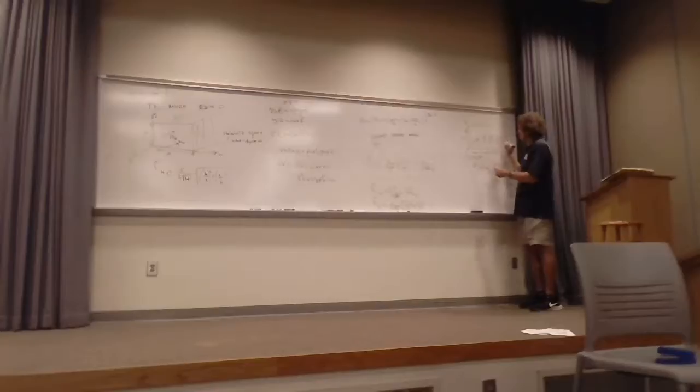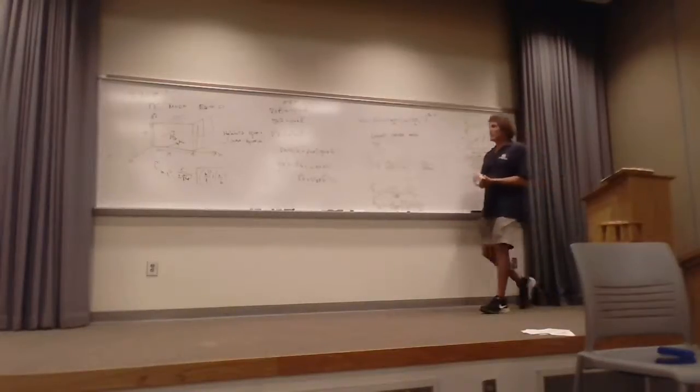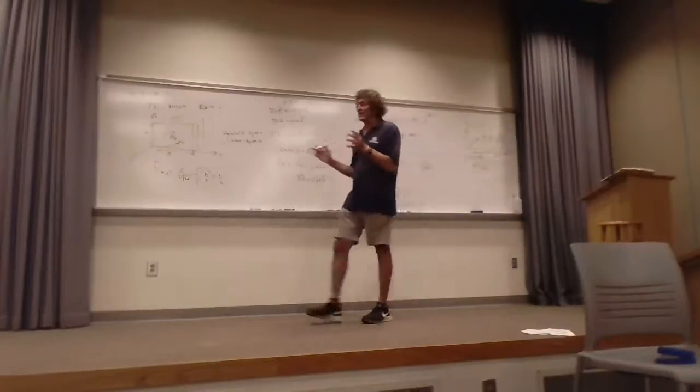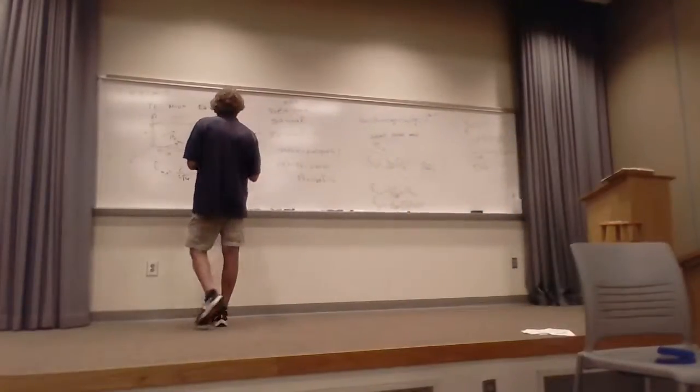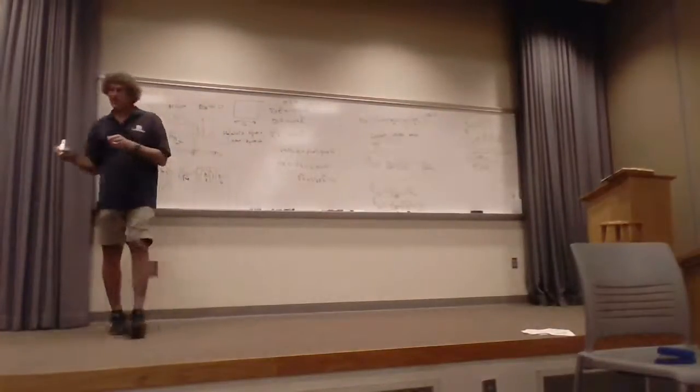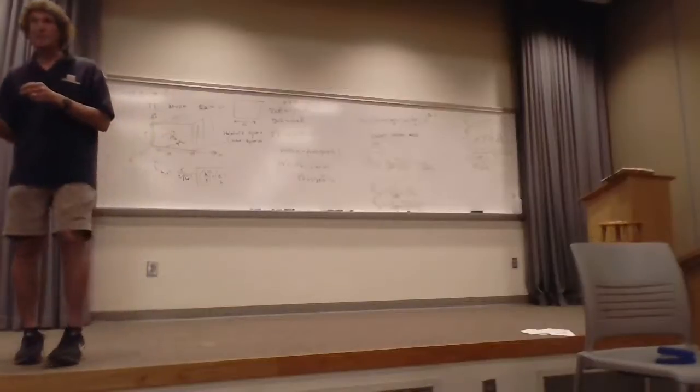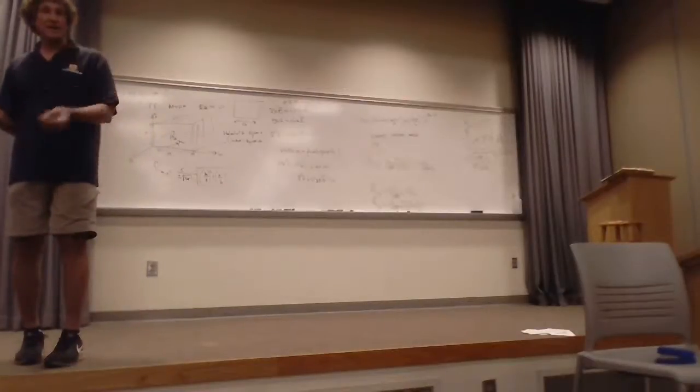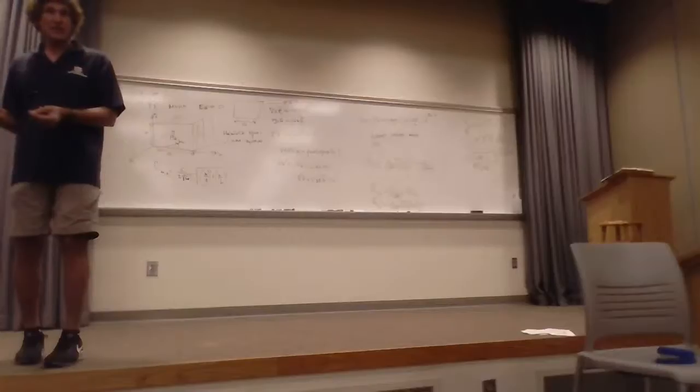And it looks like this, and this will be the actual cutoff frequency. The lowest order mode will be the cutoff wavelength by 2. So it's exactly a half wavelength long. So if I want to know what the cutoff frequency of a rectangular guide is for the 1-0 mode, the only thing I do is measure this dimension. And I say that dimension divided by 2 will be the cutoff wavelength. From that, I can get the cutoff frequency. Do y'all follow me on that, class? That would be the 1-0 mode cutoff frequency.